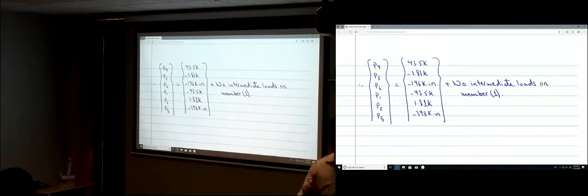So you need to transform those U's that you found from the global direction to the local direction. And that's the equation. That's T times U global. Okay? So pretty much we're just doing cosine and sine to everything inside of that matrix. Yes. The transformation matrix is only C as cosine and S as sine.